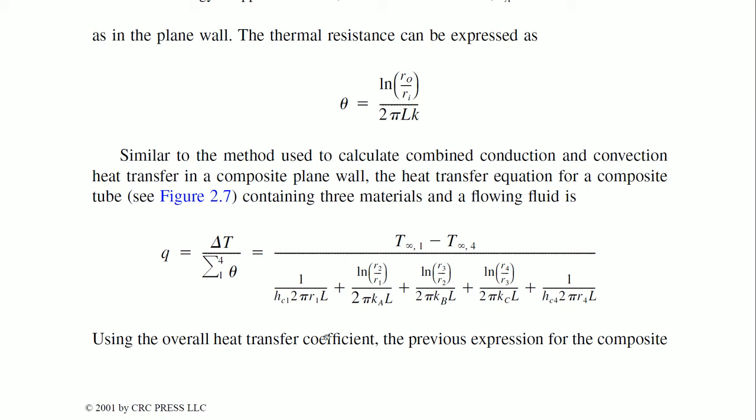What we have done by gravity die casting and sand molds will be very poor compared to something which is pressure die cast. So, if you see all your motorbike engines, invariably all the items are pressure die cast. So, the conductivity is very, very high.